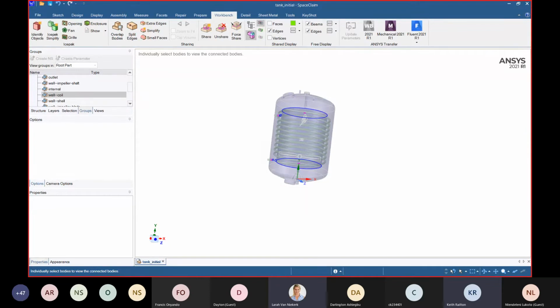So that's it, and then there's another question. Is it possible to make sizings that are relative to another? Is that question clear? Okay, so you can't. Your sizing is going to be absolute. All your local sizings you can make smaller than your global mesh, not larger, but you can't scale them relatively.